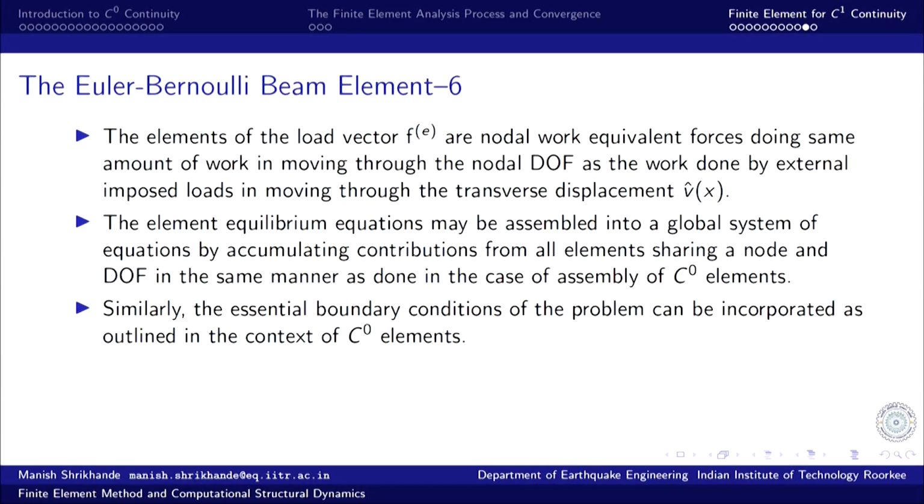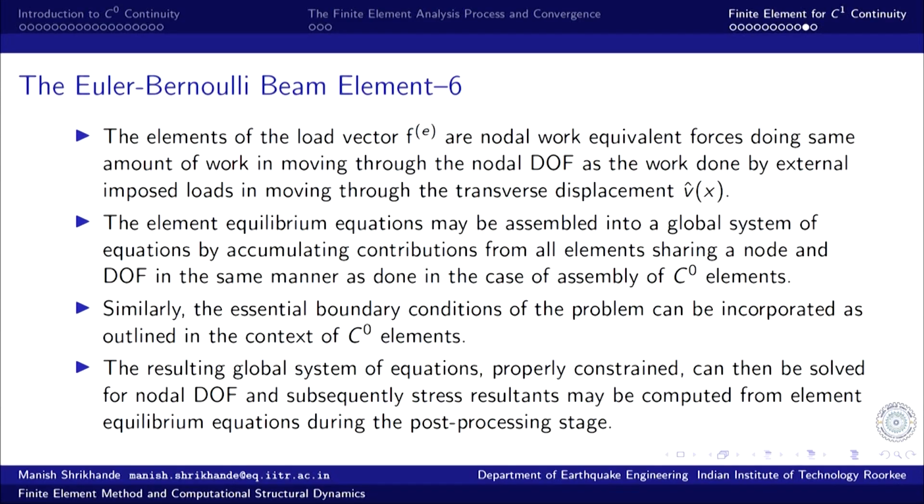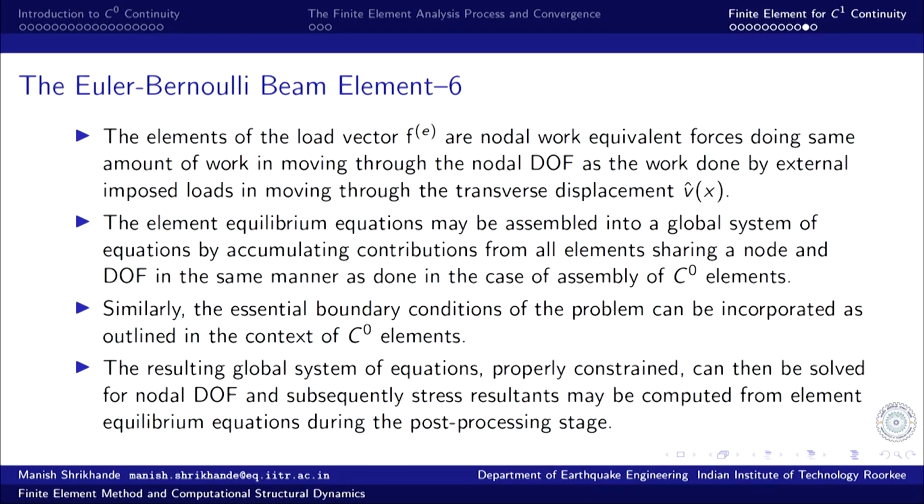And after the assembly of the global system of equations, essential boundary conditions of the problem can be incorporated, and the resulting global system of equations, properly constrained with respect to imposition of essential boundary conditions, can then be solved for nodal degrees of freedom, that is, the unknown primary variables at the nodes of the finite element mesh, and subsequently stress resultants, or the secondary variables of the problem, in different points of the domain can be computed from element level equilibrium equations during